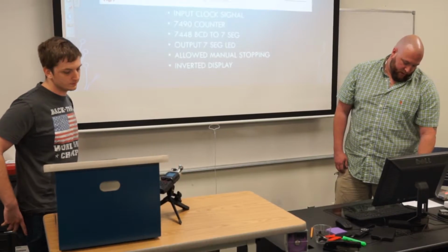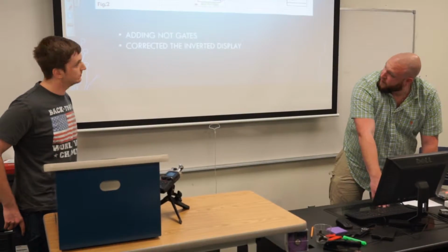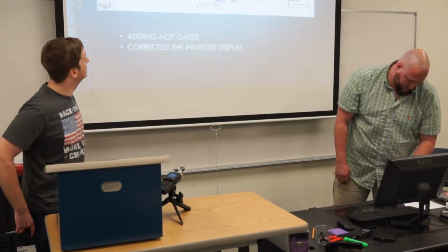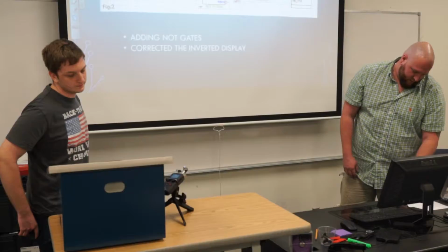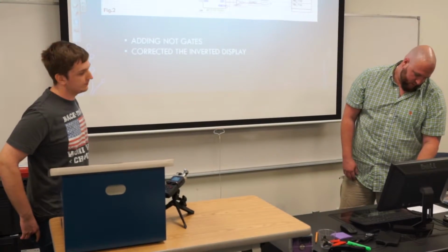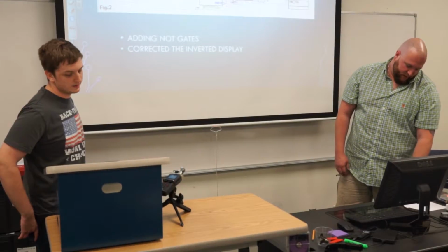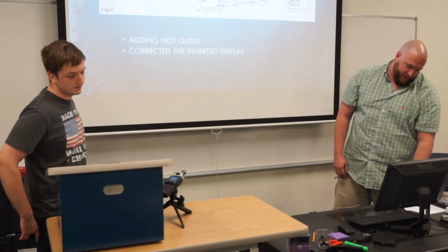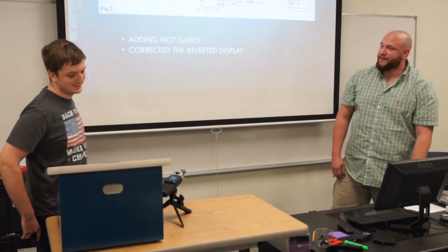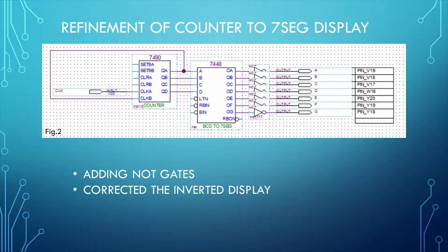We connected the output of our three counters to the 7-segment displays, and we learned that this particular chip's output had to be inverted in order to properly display numbers. Otherwise, it would display exactly what you didn't want to see: all the inverted characters on the 7-segment display.